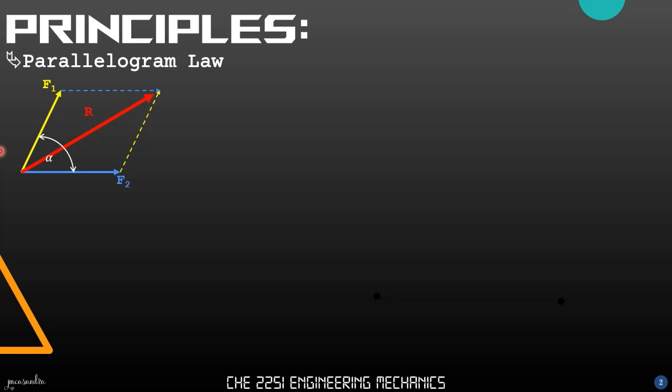With this, we could graphically compute for the resultant, or we could also analytically solve for the resultant of the forces using R equal to square root of A squared plus B squared plus 2AB cosine of alpha. For the direction of the resultant, theta, this can be solved using the equation theta is equal to arctangent of B sine of alpha all over the quantity A plus B cosine alpha.